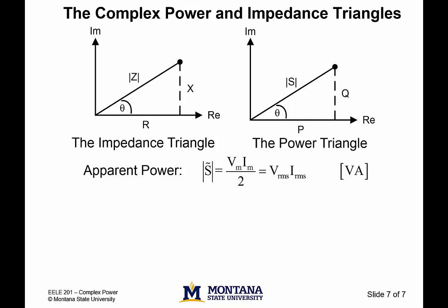If the voltage and currents in the circuit were not sinusoidal, but rather DC, Vrms times Irms would apparently be the power absorbed. This apparent power is realized when dealing with sinusoids only if the impedance in question is purely real. That is, if theta V minus theta I equals 0. A non-zero phase angle does not allow one to realize the full apparent power available.